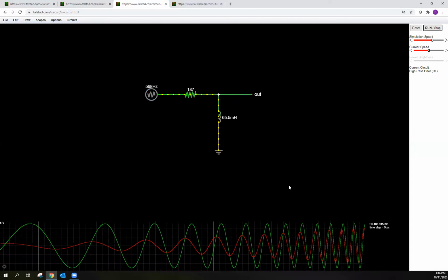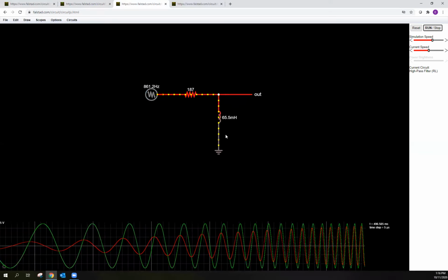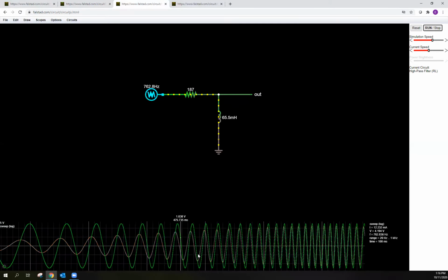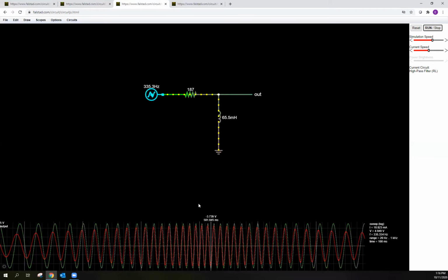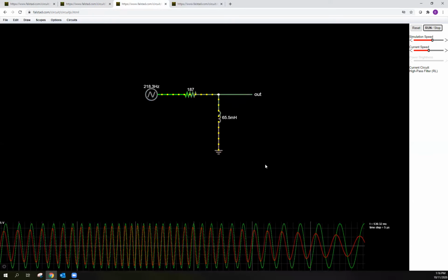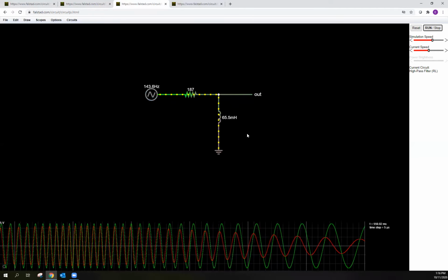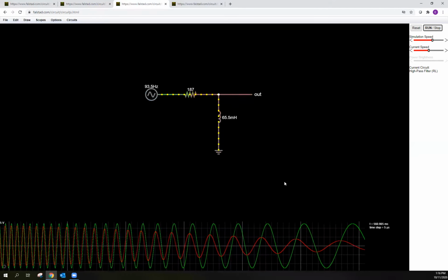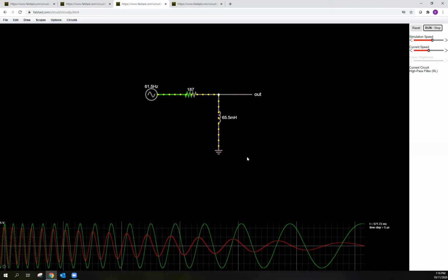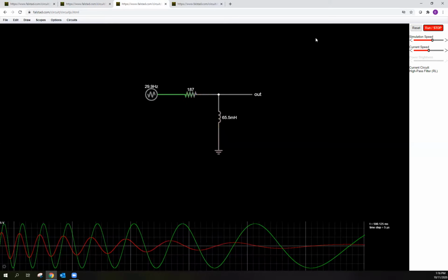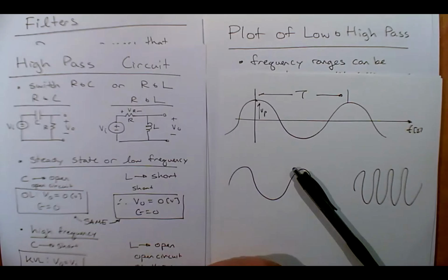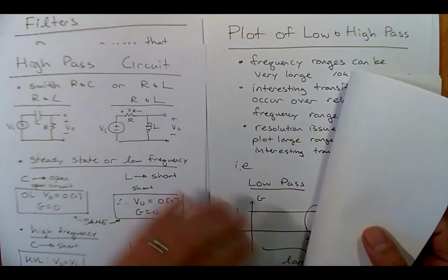And notice this one, you have a phase lead in this case. The output is leading the input by a certain amount. And we'll talk more about that later, right? Okay. So hopefully that gives you some intuition as to what's going on with these low pass, high pass filters and how we can actually implement that in a physical system. Okay, so stop this and let's go back to the DocCam. All right.